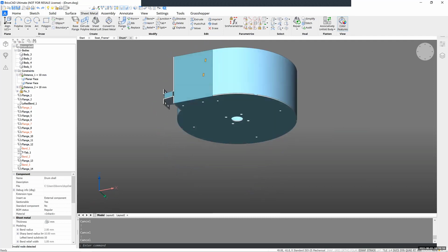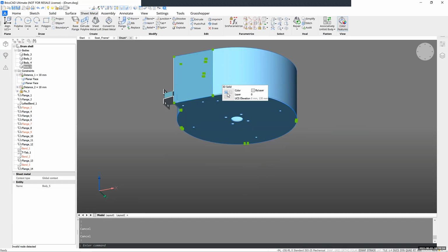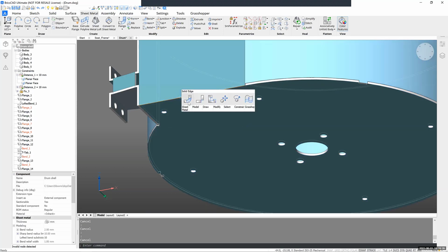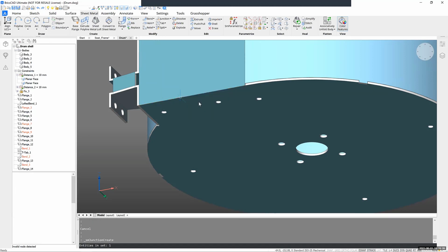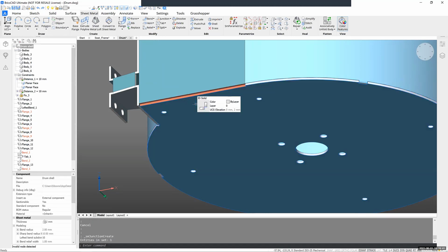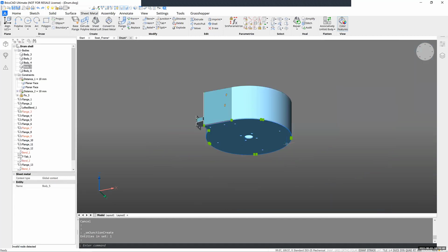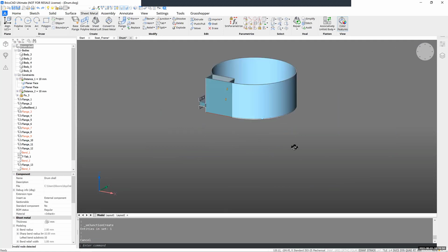So that's that. Now you would think it's almost finished. It is indeed, but you still see that if I select the bottom, the drum shell also comes along. So I still need to create this into a junction as well. And I can create the junction. And now if I control to select my entire solid, then I can create that. I can select the bottom alone. So now it's manufacturable.